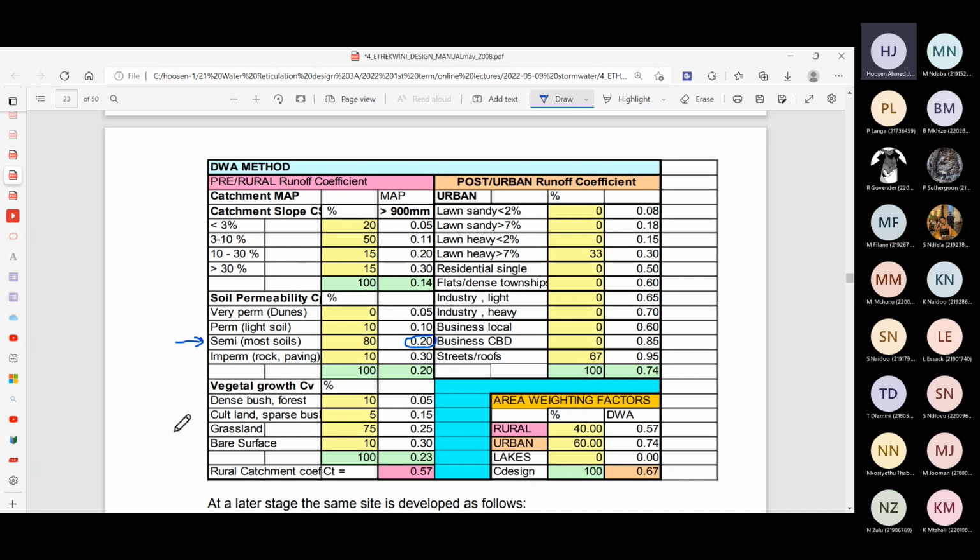So the natural thing, without being provided any further information about that area, you may look at Google Maps for those coordinates and look at it, and we would assume it's a grassland area. So that's why we're getting a value of 0.25. And again, we're putting 100 at that point. The entire catchment we're assuming is grassland, so the rest of those values would be zero. Right. So in this table, this is how we would populate it, or that's what's being done in this particular example. The same thing for the permeability. That would be 100, and the other values we're taking as zero.